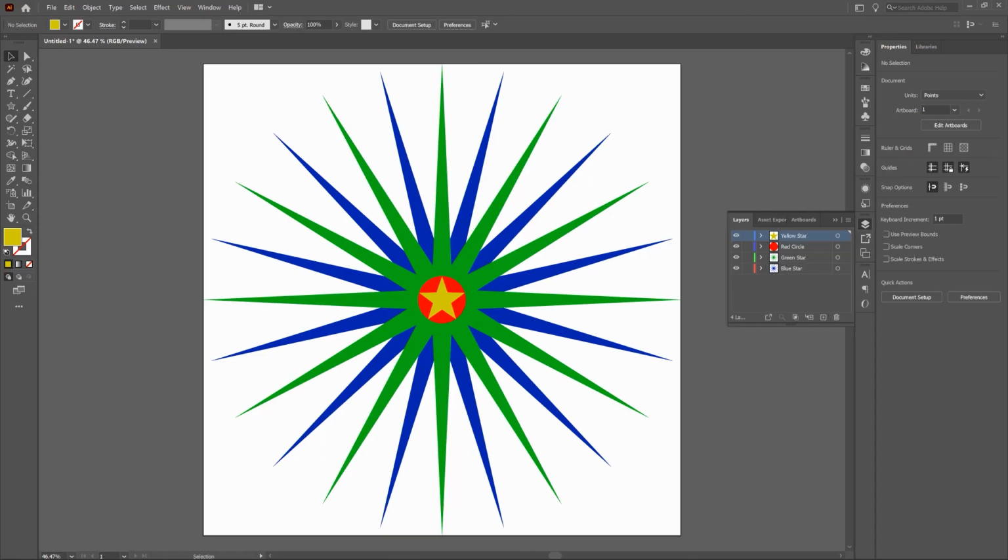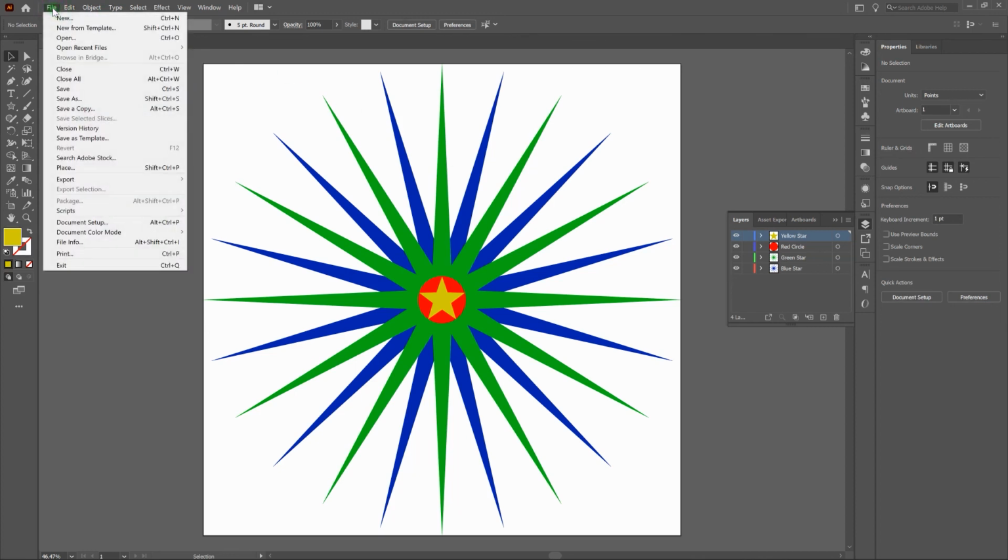One of the important things that I'd said about layers previously was that I could export my Illustrator file. One of the powerful things about layers in Illustrator is if I export the Illustrator artwork, the layers can come along with it. So that's always a good positive thing. In this case, let me show you how to do it. The way I'll do that is I'll select File, and I will select Export. Once I've done that, I'll select Export As,